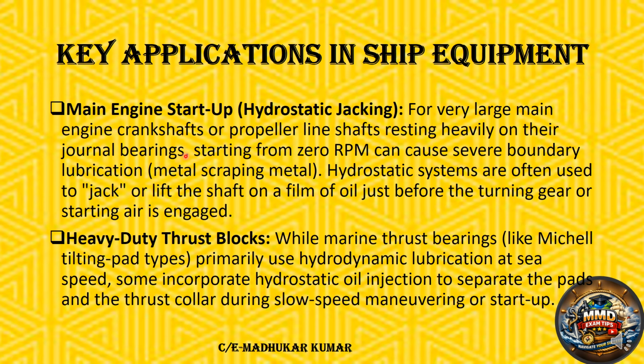So basically, in our ships, the crankshaft is connected with the intermediate shaft, and the intermediate shaft is connected with the propeller shaft, and then the propeller comes in. But all the load is resting on the journal bearings, starting from 0 RPM, because at the start the RPM is 0. If there is nothing, it can cause severe boundary lubrication, metal-to-metal contact. But what we do is start the lube oil pump, and once we start it, the pressurized oil goes in and creates the separation.